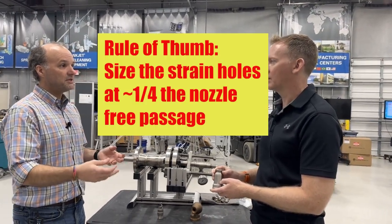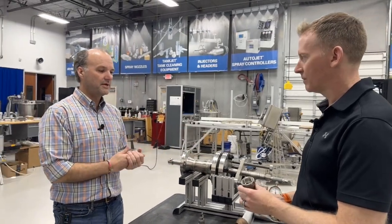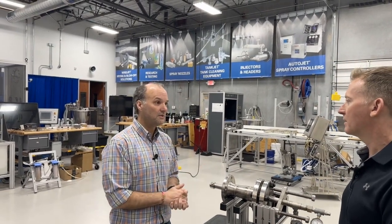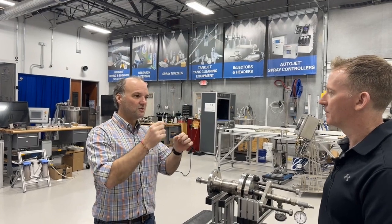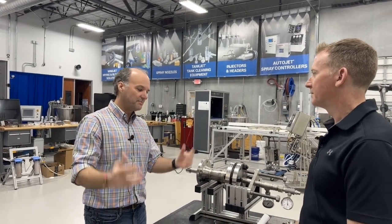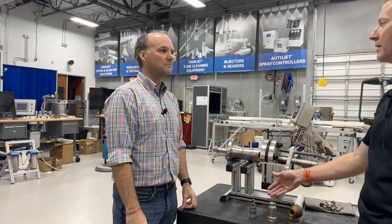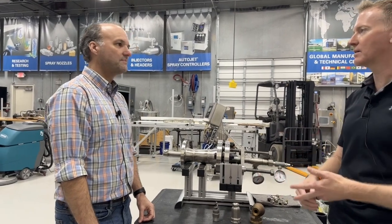So 25% of whatever that maximum free passage is. In any spray catalog, it should list what that maximum free passage is. Or if it doesn't actually say maximum free passage, you just use the smaller number that's listed, and that's going to end up being your free passage. So if this had a free passage of 10 millimeters, you would go with 2.5 millimeters as the target strainer size. That is correct.